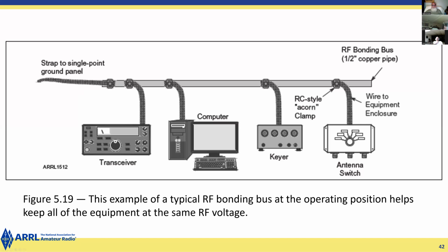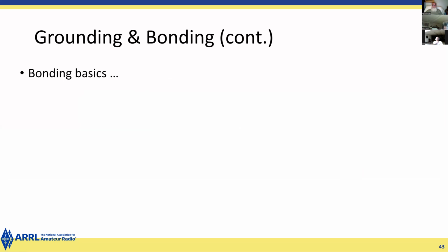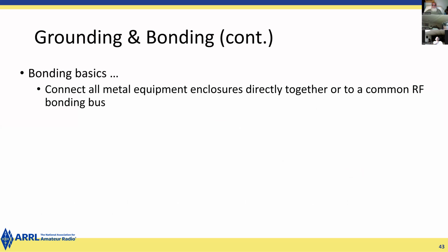Now, okay, so what you need to do is connect all your metal enclosures together, directly together.